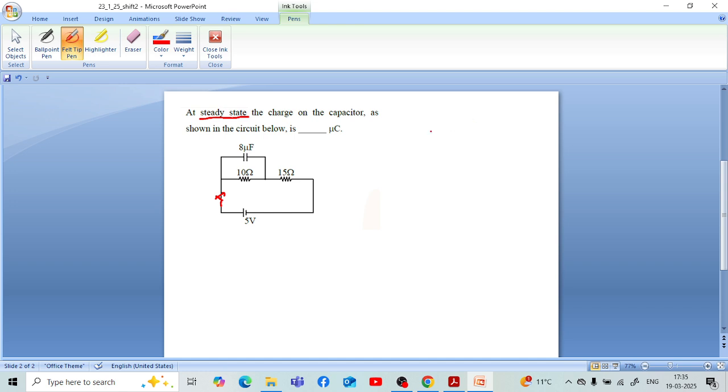So if we want to analyze the status of a capacitor in steady state, suppose there is a capacitor and we apply a DC across it, for a very long amount of time. So what happens is that it becomes open circuit. Suppose if there is a key here and we just close this key, then for just a moment it becomes charged instantaneously if there is no resistive element here, and it reaches the steady state condition after a few seconds after the charging.